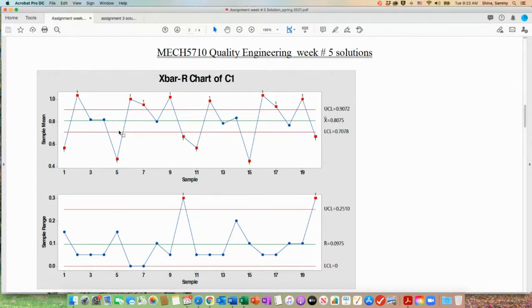Then you use that history to preserve the way production operates on day one, or the day you decided to control chart the production system. Then every day you take a sample and plot the sample average. That's the X bar. So this point is an average of 3 measurements. That's the way you set it up, and you run it every day.